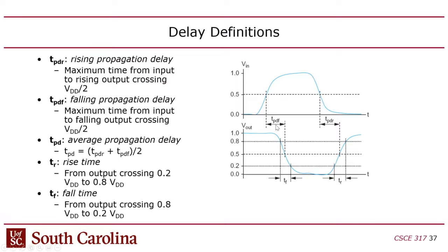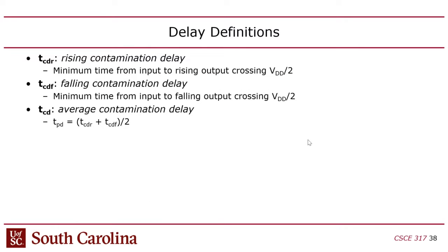But the rise propagation delay might still be equal. I'm not sure. I don't remember the rise propagation delay being longer than the fall propagation delay. I just remember, when you look at the traces, the slope is usually a little less on the rise time.